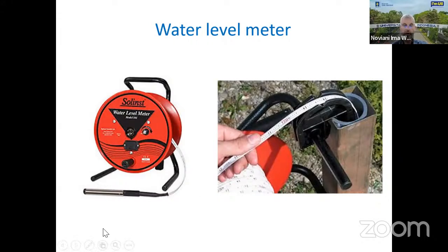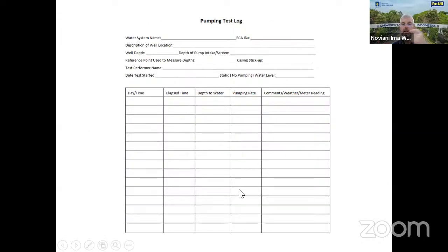And you write a report, or basically use a table that looks like this, where you report the time, let's say first hour, second hour, third hour, okay? And then here you'd write down the reading from your water level meter, 2.9, 2. Whatever. The reading is being recorded for each time. And then you look at your flow meter, the blue flow meter, remember this thing here?